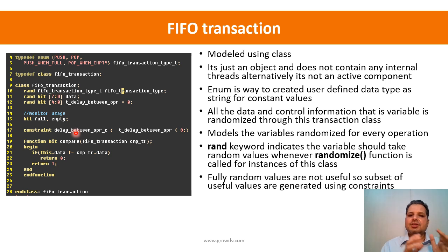So now this completes the overall picture: we have defined a driver, a generator, and a mailbox for communication between them, and we have this transaction that goes through the mailbox and is passed between your generator and a driver, and we see how this particular transaction is getting randomized. We have been talking about how we do constrained random verification, so now we are able to put the constraint and randomize the data part of it, and that randomized data is being driven out on the interface.